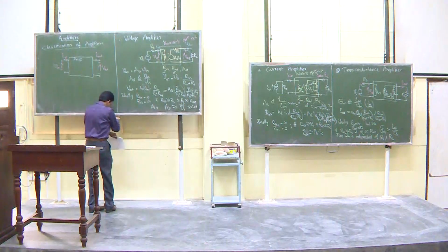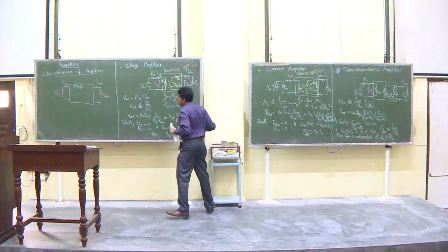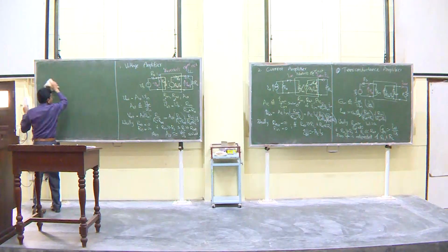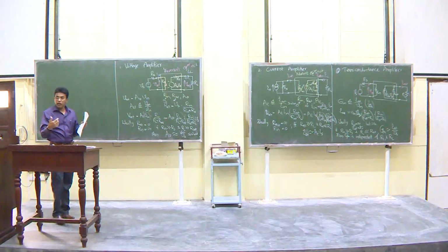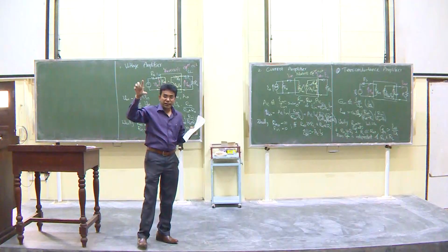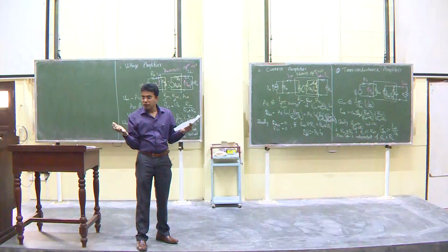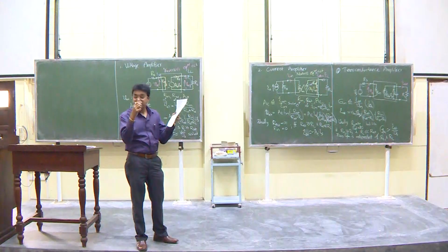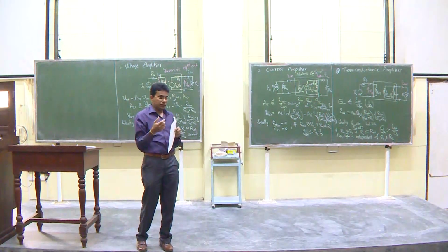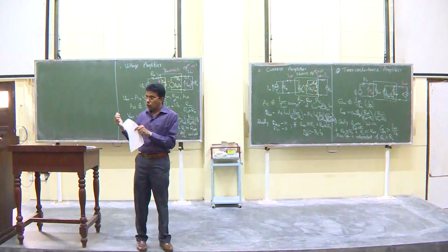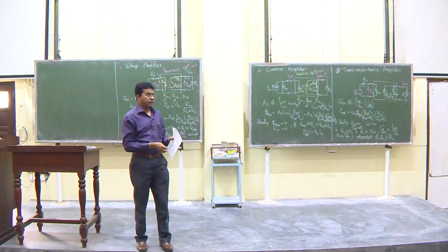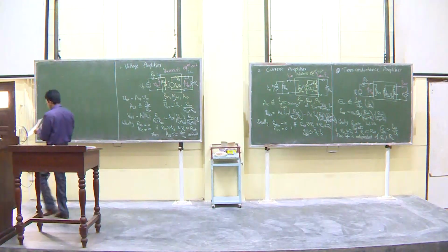So likewise, now we have the last one. Now what do we have? Input is a current, output is a voltage. So output V is equal to I times the gain. So that should be an R. Therefore the gain is a resistance. It should have the units of a resistor, in other words, ohms. So we call these transresistance amplifiers. That's the fourth type of amplifier.